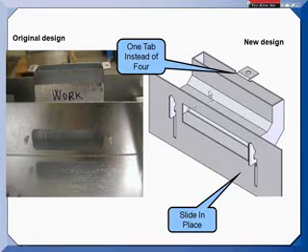We went through a design for assembly on this, and we created some alignment features. So we have these tabs now that we created. We put slots in here, and the way this now gets located is there's actually a little interference here. So it pulls the back surface of this new redesigned part up against the sheet metal, and you bring it up until you contact here and there. And we've also controlled the distance from this side of the slot to that side of the slot.